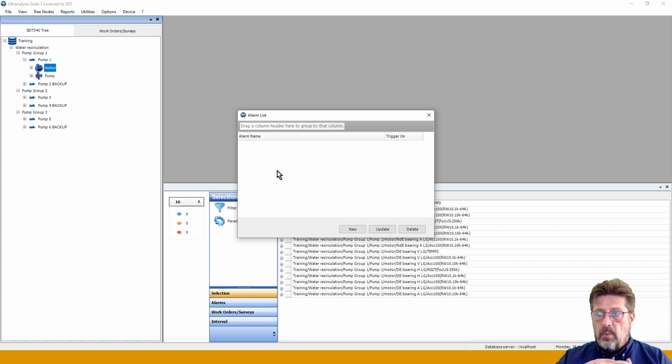Then you will basically create an alarm called conveyor bearings and attach it to all of the bearings on that conveyor, if that's the reality of the condition in the field. But one day you have one bearing behaving strangely, and you want to change the alarm. If you change that template, the change will affect all of the bearings where it's attached, and maybe you don't want that. So for that purpose, and for the purpose of customizing for each point, you will be using node alarms.